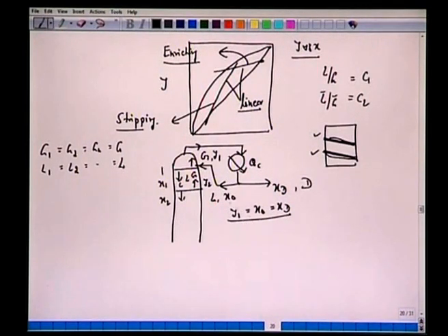All right, now we can do the same analysis which we did earlier. G1 which arrives here is the same as L plus D, the reflux liquid and the top product D. The reflux ratio R is L0 over D, but we always say this equals L by D. So no subscript here, which means we can write G as D(R plus 1).